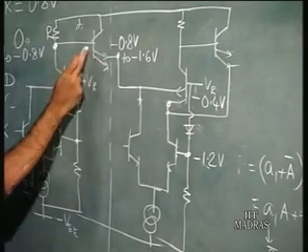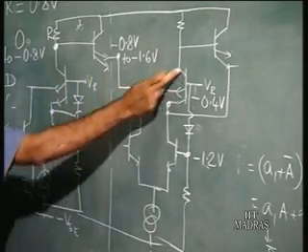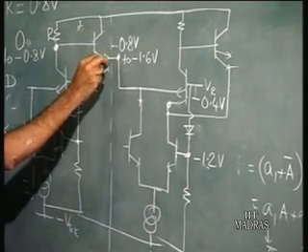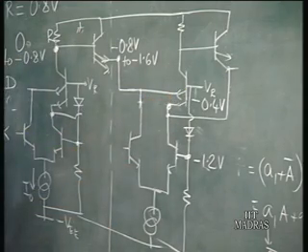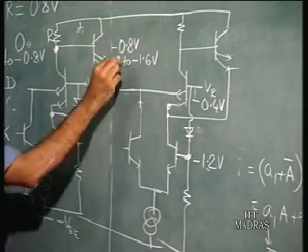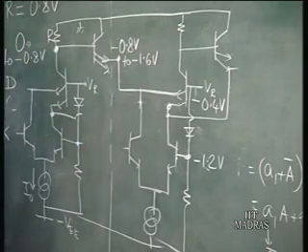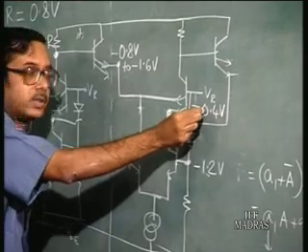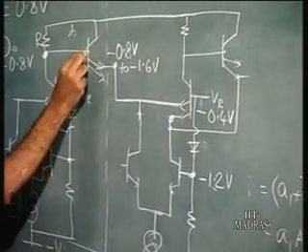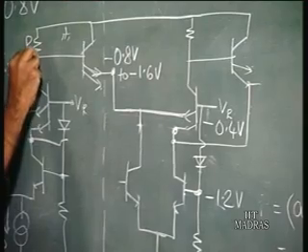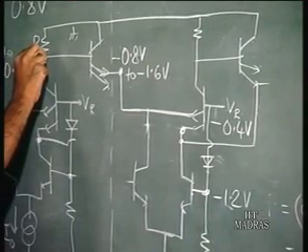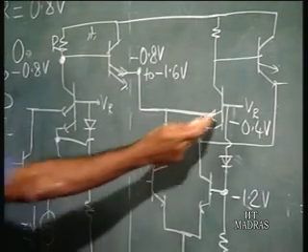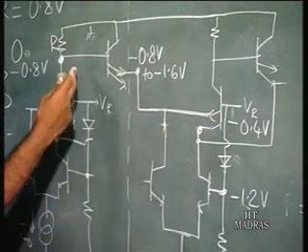Now, you have again an emitter coupled structure here. This transistor, that is the output transistor of gate 1, and this transistor form an emitter coupled structure. The emitters are shorted here, you see. And this input here is minus 0.4 volts, and the input at the base of this transistor is varying from 0 to minus 0.8 volts. So, what we are having is a variation of this VR plus minus 0.4 volts at the base here.